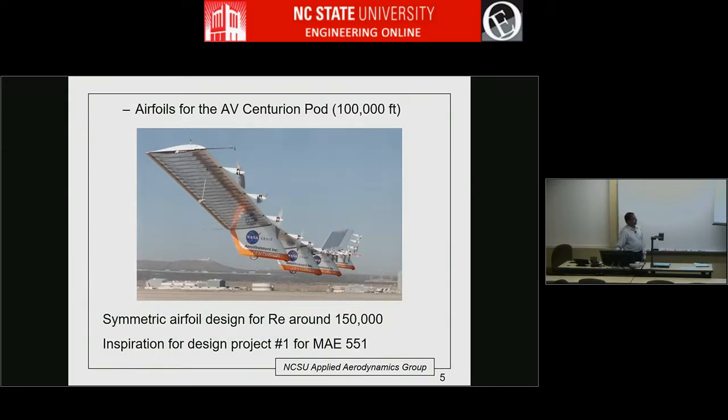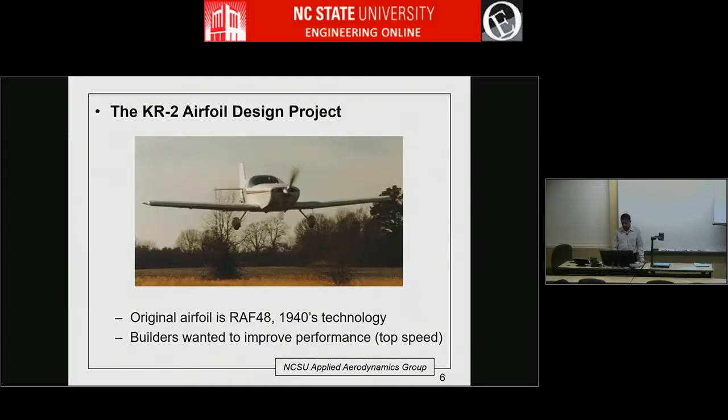But when you have to design airfoils for aircraft like this that fly at very high altitudes, this one went almost to 100,000 feet, then these are the sort of problems you have to handle. And then this is an example where I got a chance to design an airfoil for a general aviation aircraft. And here laminar separation bubble is not really a big problem. It is much more a problem of trying to keep as much laminar flow as possible to reduce cruise drag.